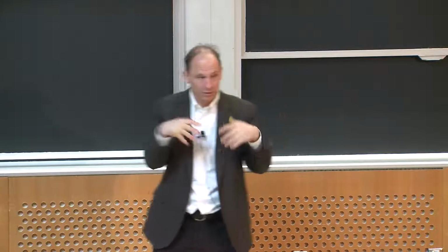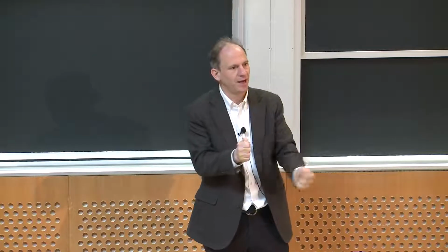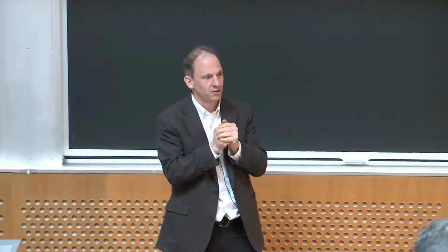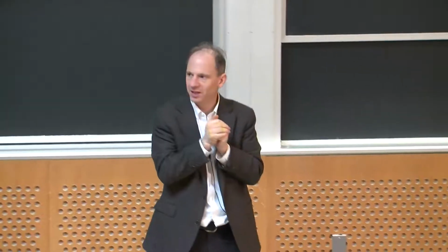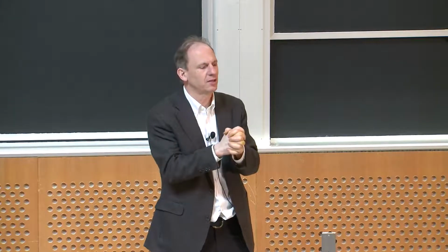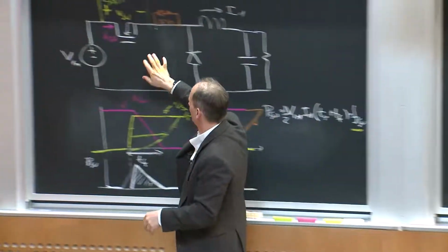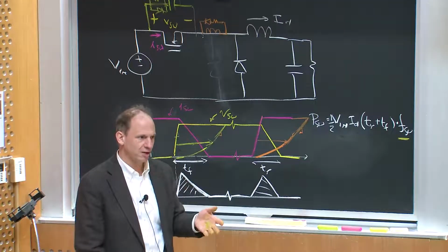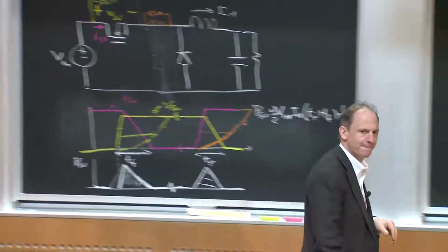In the real world, if you were to build one, you might build it and then say, oh, I'm getting a little bit too much EMI, and I associate that with the slew rate of the voltage, for example, and then I might go in, throw in a small snubber to slow down the voltage transition. So sometimes people will leave provision to put a snubber in if they need it in practice, but it's not something you would necessarily have to design up front unless the types of devices you were using required it. And that would be typically very high power devices that are a bit more fragile. For MOSFETs and Schottky diodes and stuff, typically you don't have to worry about it. Excellent question.